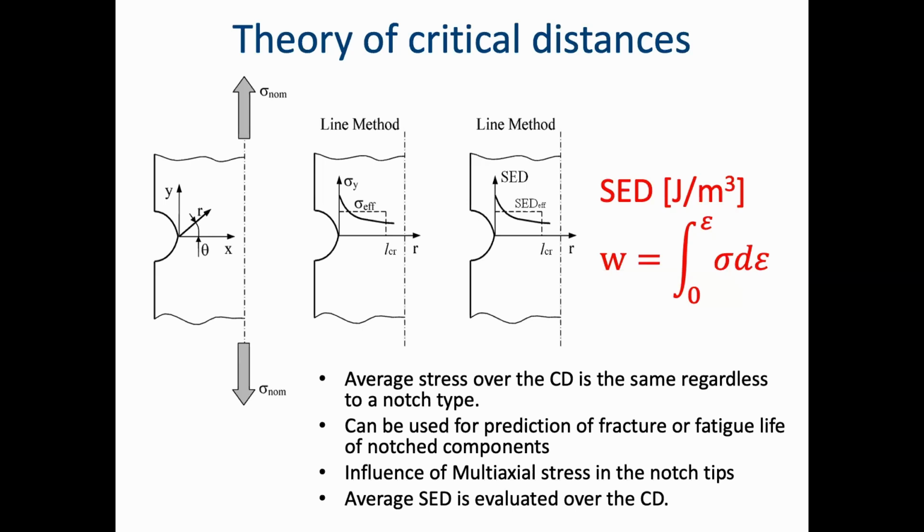The specimen is loaded in axial loading, and here is introduced the line method of the theory of critical distances, where the stress distribution is drawn, and this stress is evaluated over some critical distance. Similarly, we can evaluate over this distance also strain energy density.